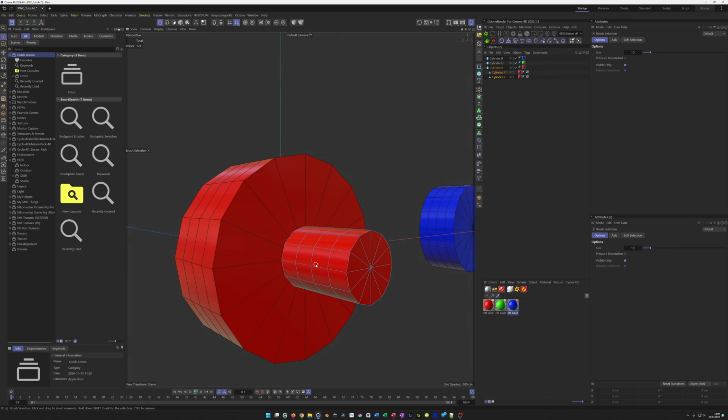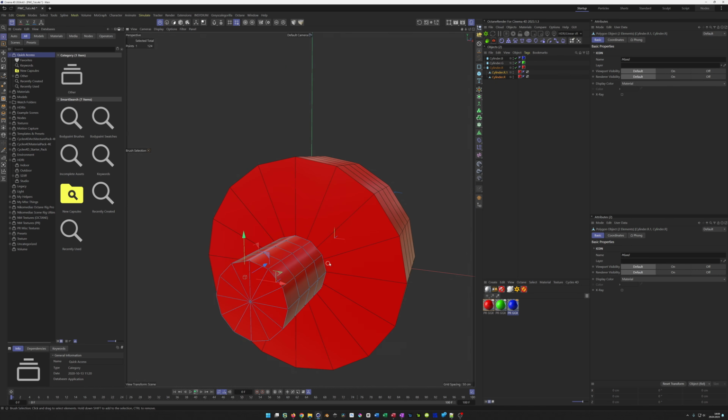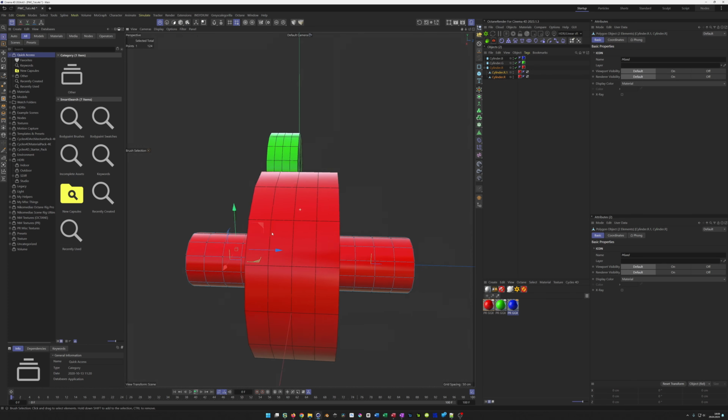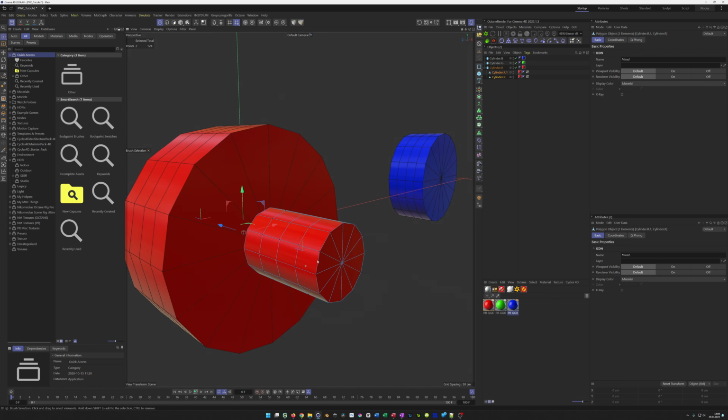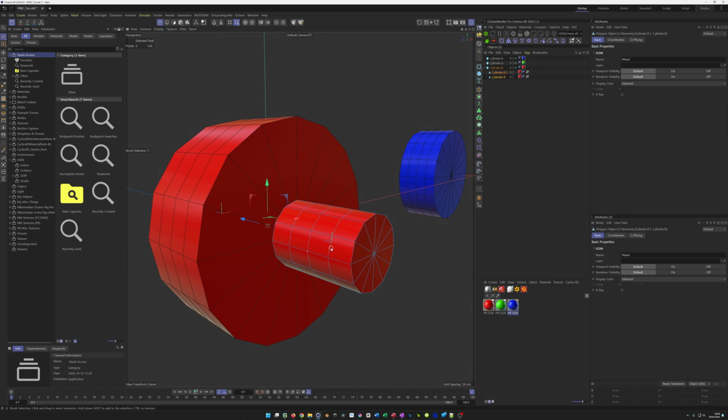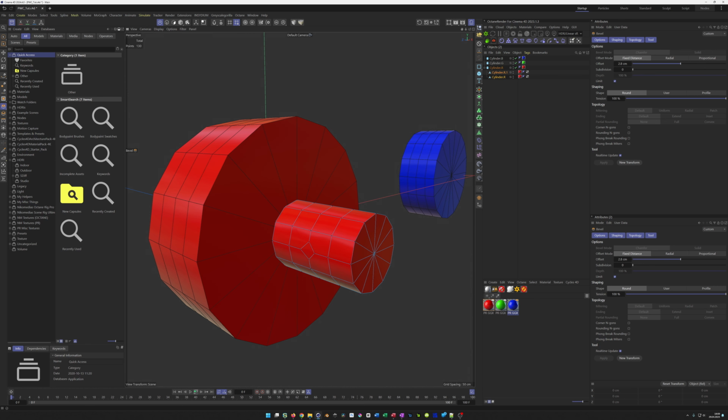And I select this point here, and I select on the other side this point here, so where it comes out. And now I bevel this out. Something like, let's say the 7 could be a good number here, but make it 5, so we have a 5 mm here. And 5 is okay, so that we don't have too thick linkages.